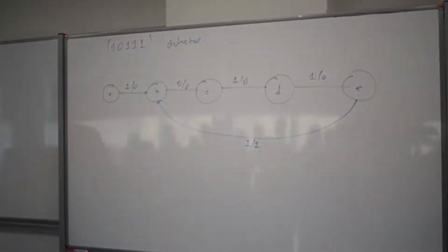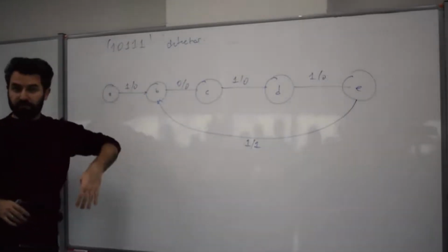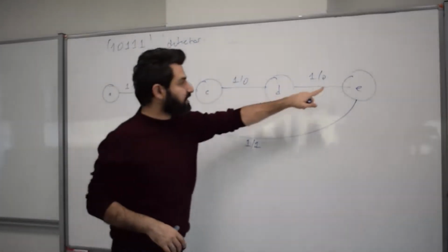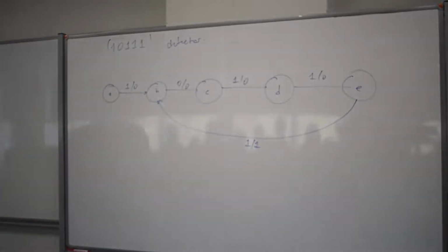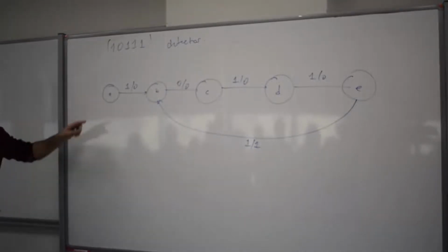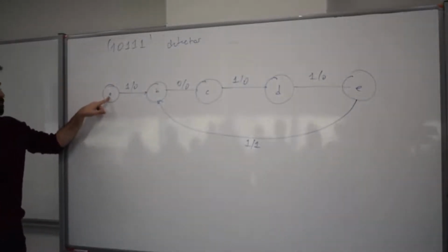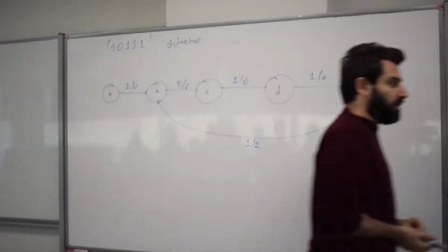So that's the first thing you need to do before you complicate your finite state machine representation even more with other arrows. That's the first path you need to draw. I call this the valid sequence path, and the valid sequence path has to be drawn first before you even think about other possibilities in each one of these states. For instance, in A, you know where to go when the input is 1, but you don't know where to go if the input is 0. That is the extra detail you need to add.